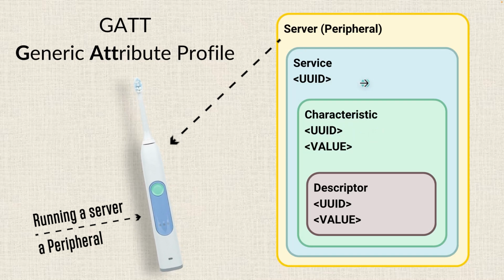And since service and characteristic weren't enough, we can also have descriptors, and a descriptor is assigned to a characteristic. So a characteristic can actually have one or more descriptors. It doesn't have to have any, but it can have a bunch. And what the descriptors do is they add metadata to the characteristic. For example, maybe it'd be like time in milliseconds, right? This would be like, oh, hey, that value is meant to be milliseconds, something like that. Or if it was a temperature, Fahrenheit or Celsius, that kind of thing. Notice that the descriptor also has a UUID.